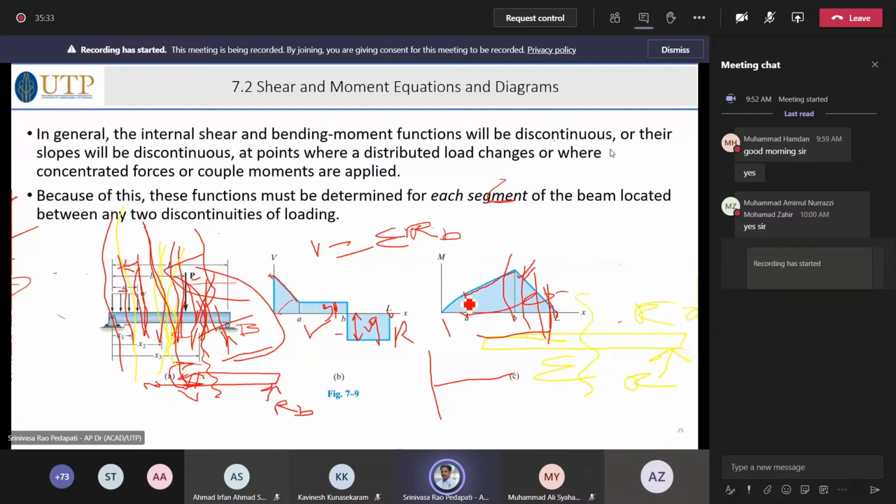Once the other load comes into the picture, this is parabolic, quadratic, because x into x by 2 is the moment. The moment created by a load of a per unit length over x is a times x, and the load is acting at a distance of x by 2. That means ax into x by 2, that is ax squared by 2. So here the moment is increasing or decreasing in the form of x squared by 2. This is how we represent the net force on the beam in the form of a graph. But the remaining equations are the same.